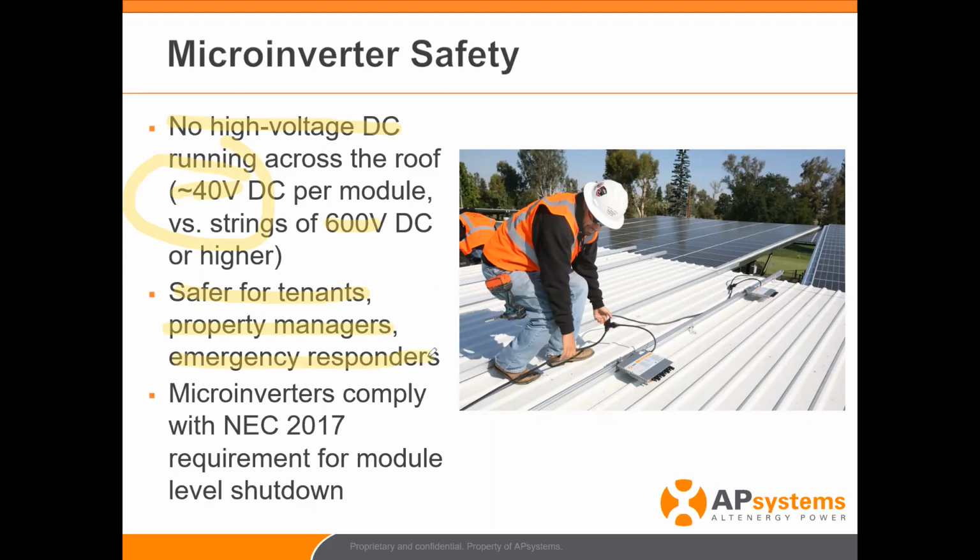Low voltage, all AC. When AC is removed, it kills the device for rapid shutdown, 690.12, within 1/10 of a second. And like I said, more importantly, it meets the NEC 2017 module level shutdown as well.